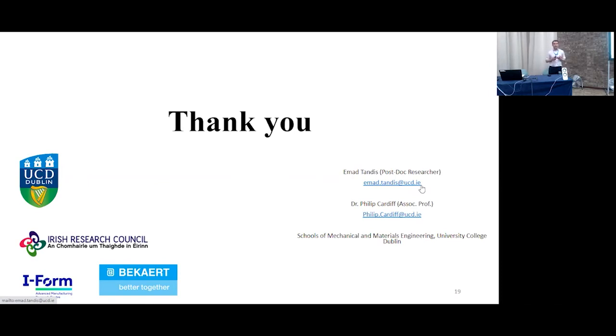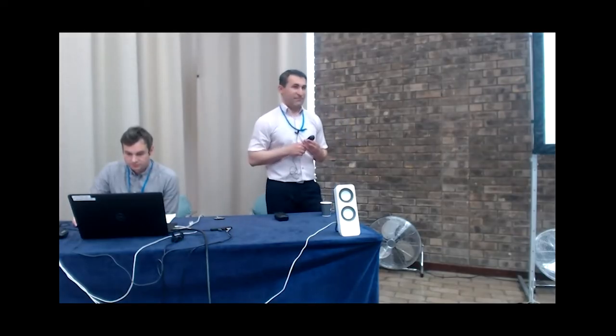The output, exactly. Interested in, I don't know, displacement probably. Yeah, displacement. The displacement field could be decomposed using the proper orthogonal decomposition into some spatial modes and parameter-dependent coefficients. If you have 500 solutions on a mesh with 10,000 cells, then the dimension of the spatial mode will be 10,000, but you will have only 500 coefficients. So this can reduce the problem.